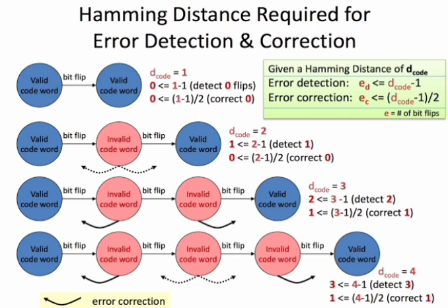The generator matrix G bar is used in the encoding operation in the transmitter. The parity check matrix H bar is used in the decoding operation in the receiver. Properties of linear block codes, LBCs. An LBC remains unchanged if the generator matrix is subjected to elementary row operations. You can form a new code by choosing any two components and transposing the symbols in these two components. This gives a new code which will also be an LBC. Two block codes are equivalent if they are the same except for a permutation of the code word components, with generator matrices G bar and G bar dash.